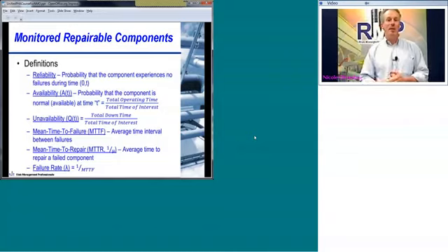So the initiating event, or what starts it, is typically represented as a frequency, or so many events per year. The safeguards are typically represented in terms of an unavailability, basically the fractional time that a specific safeguard is unavailable. Because the numbers are low, it simplifies the statistics and allows you to do the calculations a lot easier. And that's the value that you're typically using to correlate to your risk ranking matrix.